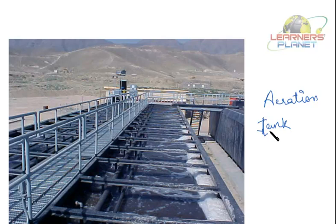Secondary treatment technologies include the activated sludge process, variants of pond and constructed wetland systems, trickling filters and other forms of treatment which use biological activity to break down the organic matter, and in this way they also digest the sludge.